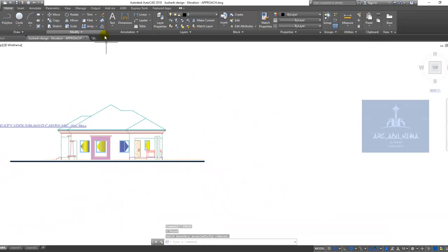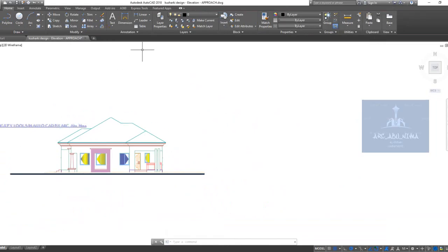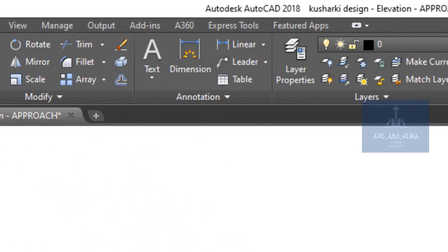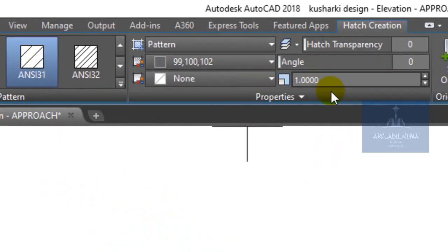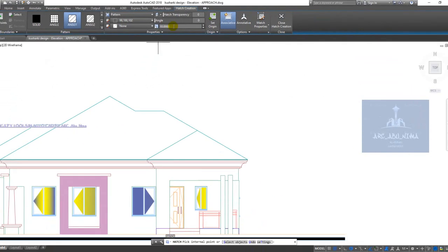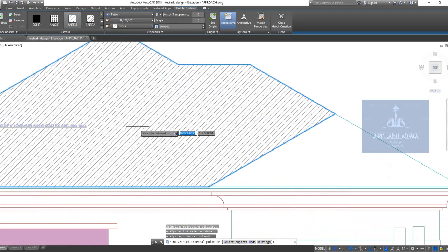so that I will use the aluminium corrugated roof pattern. You can also achieve that by using some of the patterns here. Okay, like this one now. So let me increase the scale. That's why you're not seeing it. Let me say 10. Okay, still small. So you'll be making some settings with your scale. Let me say 20 now. Okay, I think 20 is a bit okay.